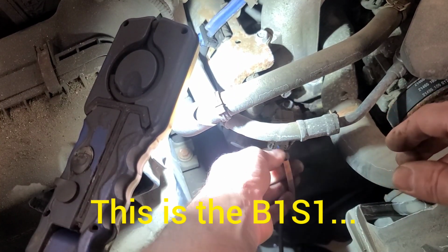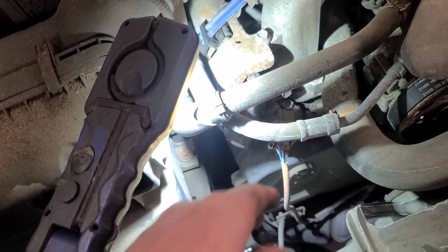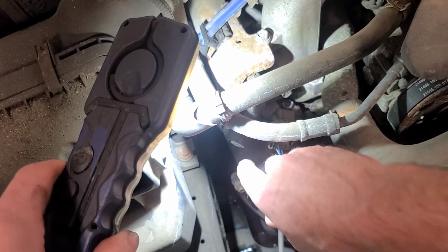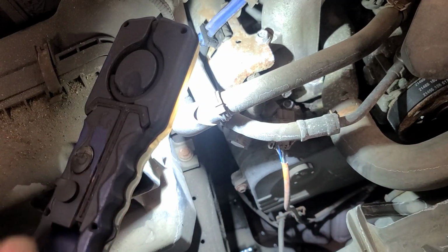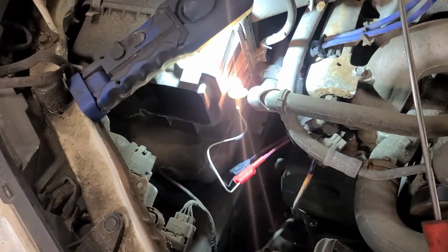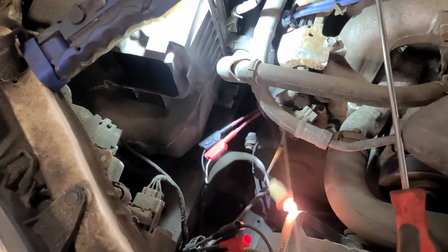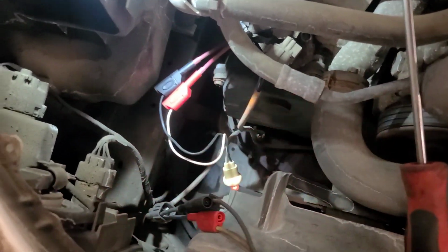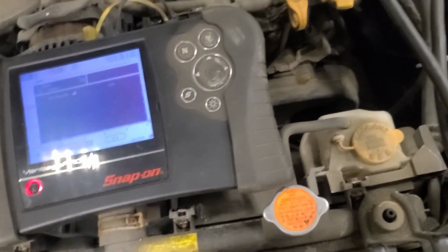Let's see if I can unplug that one. Or better yet, put a test light across the 2 pins on here that the O2 sensor heater would actually activate and see if it lights a test light. I'm going to see if I got a light that'll fit in there. So you can see that the heater circuit is pulsing. I've got the 194 bulb connected across there. I'm curious if the code will go to history now.